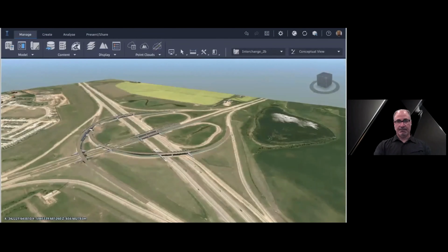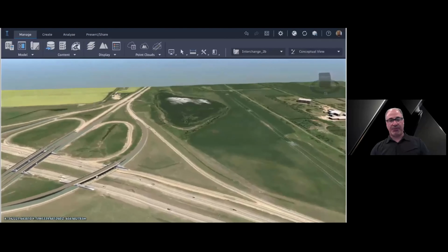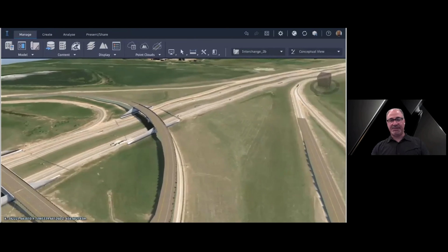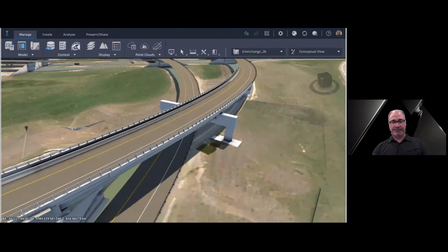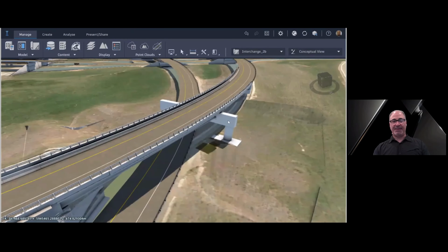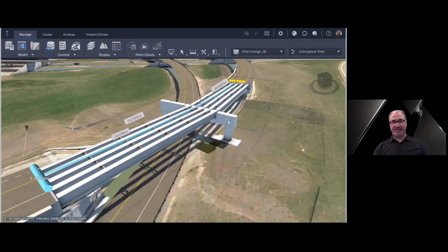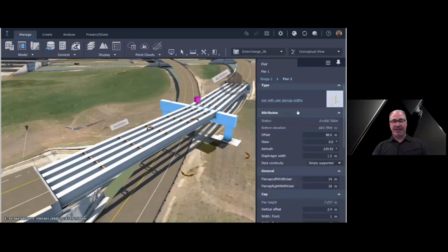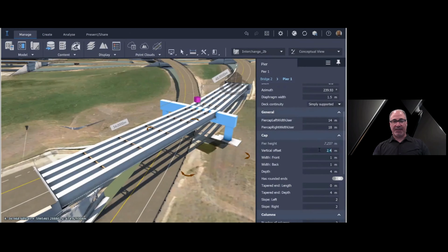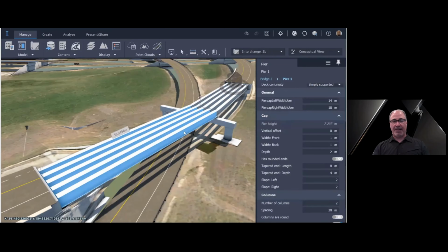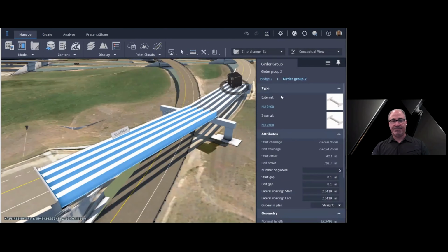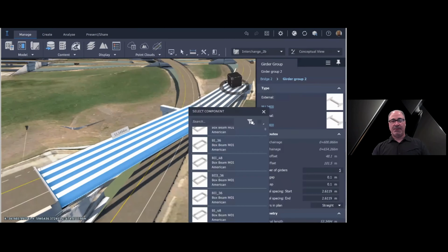And the next part is to show that, even though we can vary the geometry of concrete girders and steel girders with slices, sometimes you need a lot more precision, or you have to handle much more complexity. So let's take this concrete bridge with the pre-stressed I girders and make it change. Suppose we're modeling an Australian ANZ type of Super T bridge. These Super T pre-stressed girders are far more complex geometrically than can be represented by 2D dimensions that vary along the span.